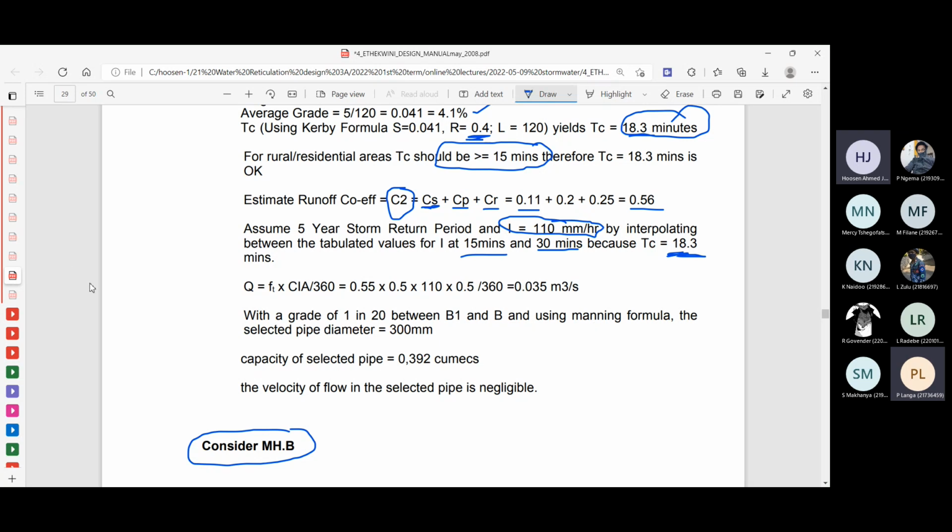Then, plain and straightforward, you can work out the flow, 0.35 cubic meters per second. You now just substitute into this equation here. The return period value is still 1 in 5 years, so we'll use the appropriate factor for that. I think it was 0.55, if I recall. Yes, that's 0.55 in that formula. So it's plain, simple substitution, and we can then calculate the flow.